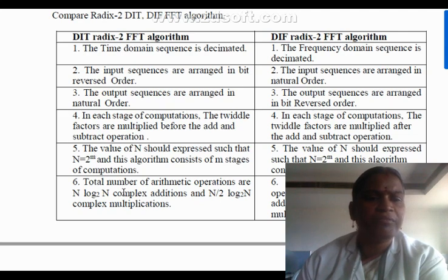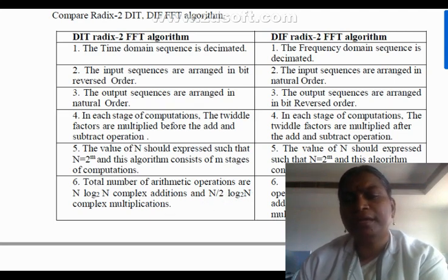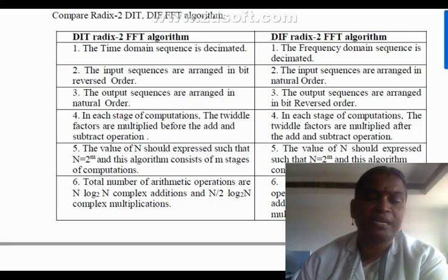Here we consider the total arithmetic operations: n log 2 n complex additions and n by 2 log 2 n complex multiplications, in both the DIT and DIF methods.